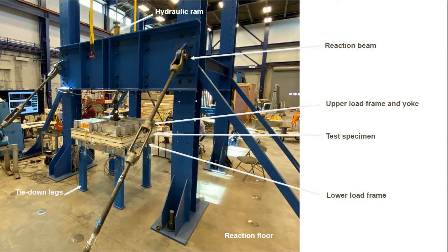on the insulation samples. But so you see up top, there's that hydraulic ram, and then that connects to the samples through a cable that was brought down through that reaction beam there, and the two sides of the frame, and with the test specimen, and then you see the tie-down legs. So the sample and the tie-down legs are completely independent of the whole frame there, and all this is attached through the reaction floor that's in our lab, which is a 18-inch thick concrete, heavily reinforced.